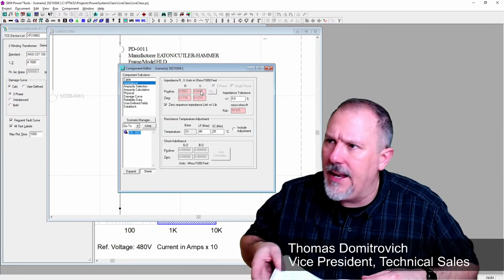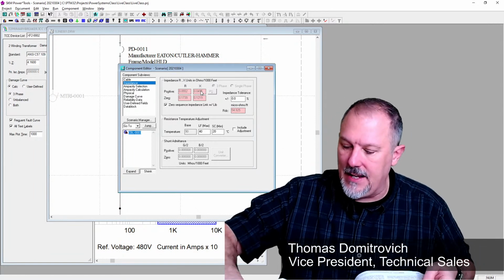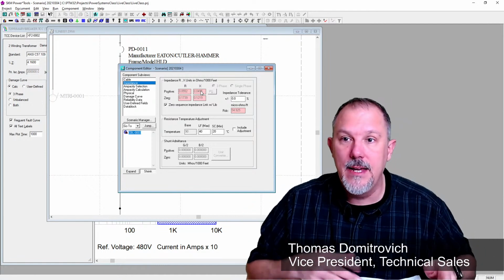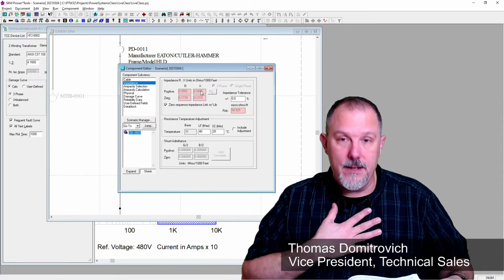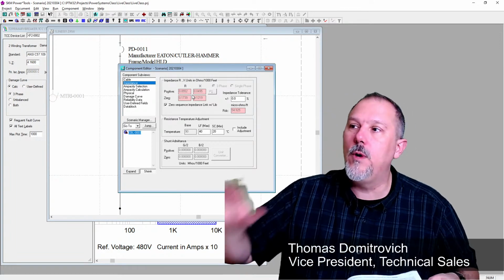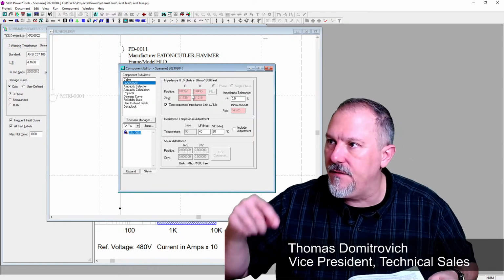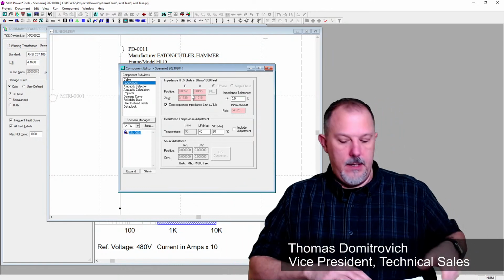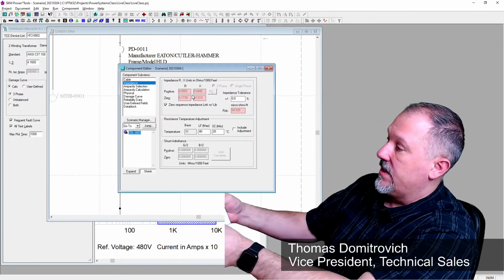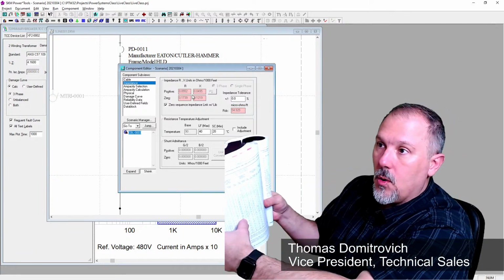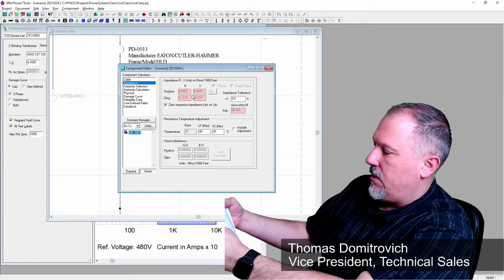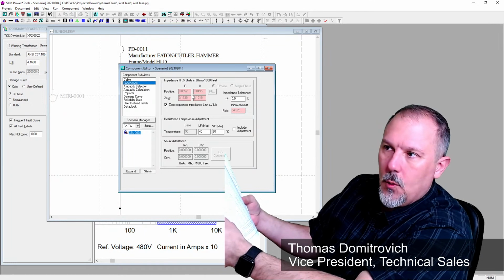Now the impedance values. If I look at a 250 back in Table 9, remember Chapter 9, Table 9 gives me my impedance values, and impedance values are important for short circuit calculations, right? What SKM uses is 0.0552. So for 250s, the resistance is 0.054 in the book, and then the X is 0.052, and they have 0.049.